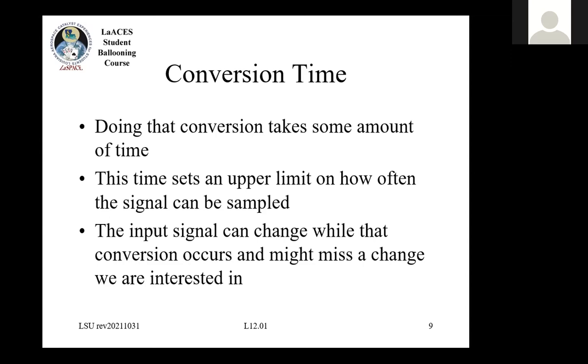I'll definitely be able to see those changes. But if I'm looking for something that is changing on the order of microseconds, well, now I probably need different hardware than just a really cheap off-the-shelf ADC, even though a lot of those are actually quite fast these days.